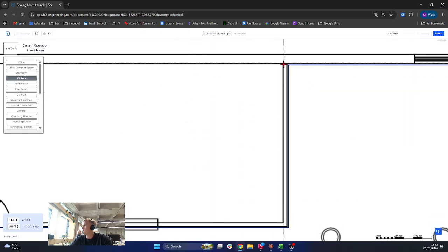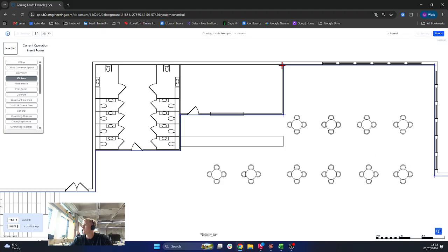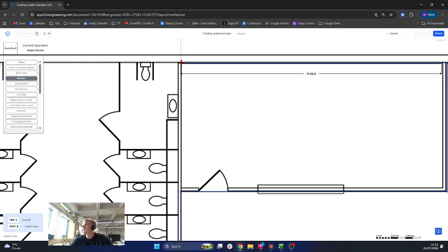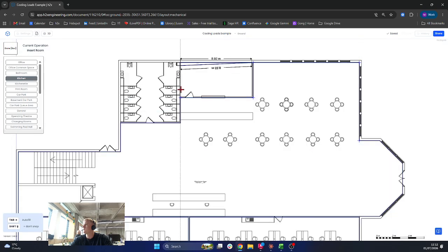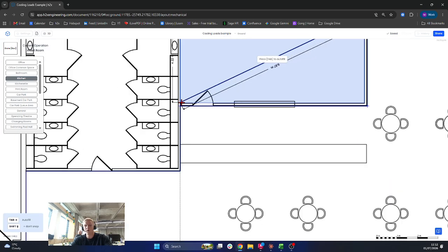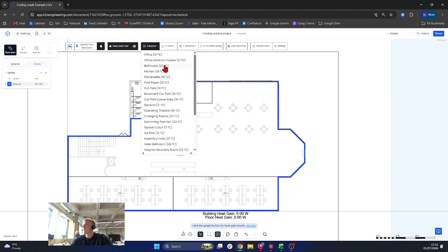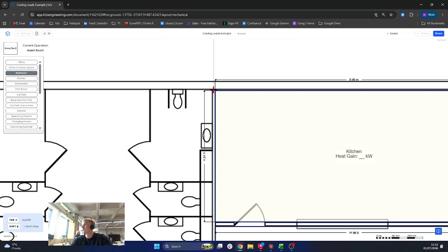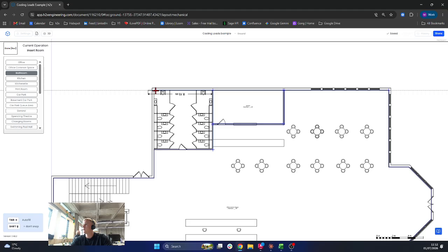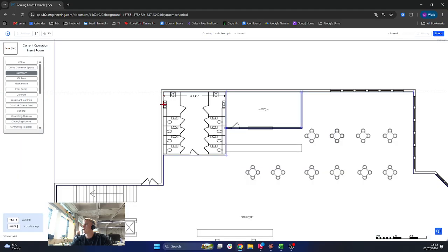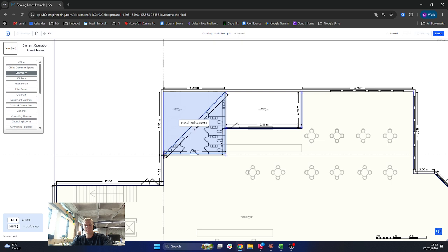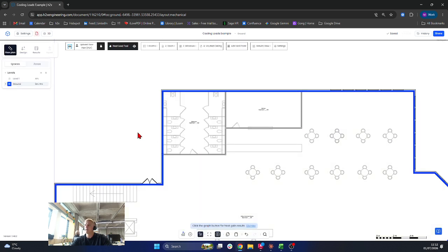Oh yeah, kitchen. Line that up with this point here, bring that across. You can see we get the guideline up at the top to give us a vertical alignment with the bottom there. Hit tab to automatically snap that into place and fill in that last corner point. We can also grab the bathroom, line that up, bring that across, get our alignment point for the other corner. Hovering over it, left click there, bring that down, hit tab, and that's been drawn in.